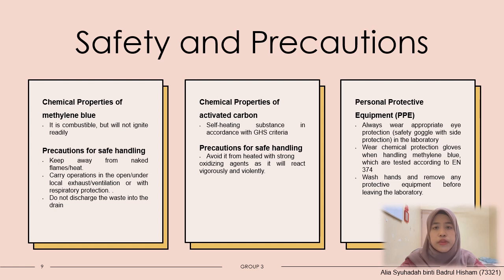Next, chemical properties of activated carbon. It is a self-heating substance in accordance with GHS criteria. The precautions for self-handling of activated carbon: avoid heating it with strong oxidizing agents, as it will react vigorously and violently.